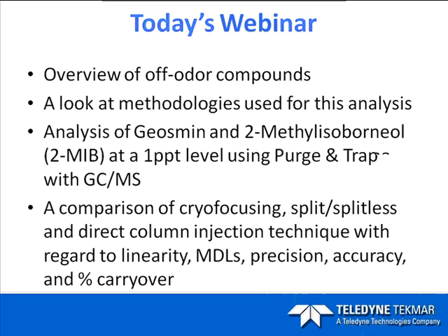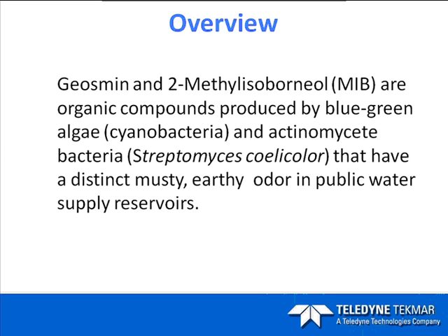Now, Geosmin is produced by several classes of microbes, including cyanobacteria, blue-green algae, and actinobacteria, especially the streptomyces, and is released when these microbes die. Now, communities whose water supply depends on surface water can periodically experience episodes of unpleasant tasting water when a sharp drop in the population of these microbes releases Geosmin into that local water supply. Geosmin is also responsible for that earthy taste of beets and contributes to that strong scent that occurs in the air when rain falls after a dry spell of weather.